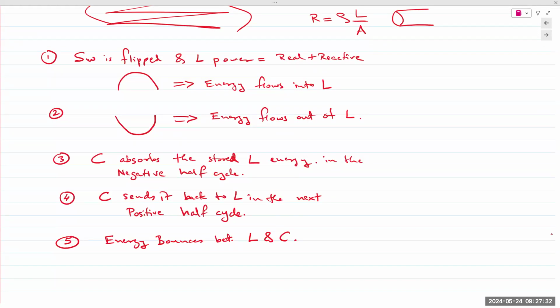Okay. So the utility company does not have to send that reactive power again and again and again. So you have accomplished two things. You have lowered the costs associated with sending the reactive power. Second, you are preventing power loss that occurs every time the energy goes back and forth. And remember, even at a low 60 hertz transmission frequency, that's 60 cycles in 1 second, meaning in 1 second, that energy would travel back and forth 60 times. So imagine if it's on for 24 hours a day, how much energy is being lost.